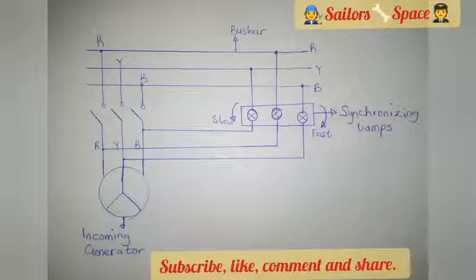The synchronizing lamps are always connected in such a way that the red phase is connected to the incoming generator's red phase, and the yellow and blue phases are interchanged in alternate pattern. That is, the yellow is connected to the blue phase while the blue phase is connected to the yellow phase. So how do you use this to know the correct moment for synchronizing?